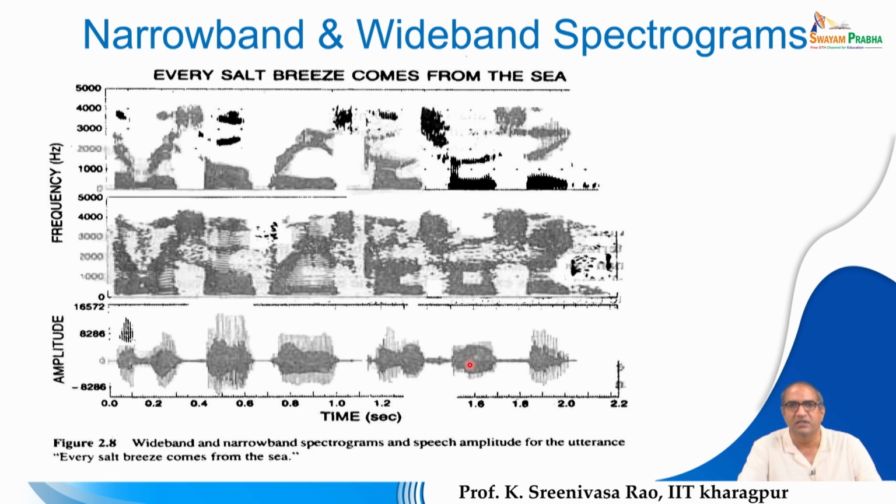If you zoom the signal in horizontally, stretching it, you can see the periodic patterns, the peaks separated like striations. Wherever the amplitude was higher, those regions mostly correspond to periodic patterns, and that is nothing but voiced speech.